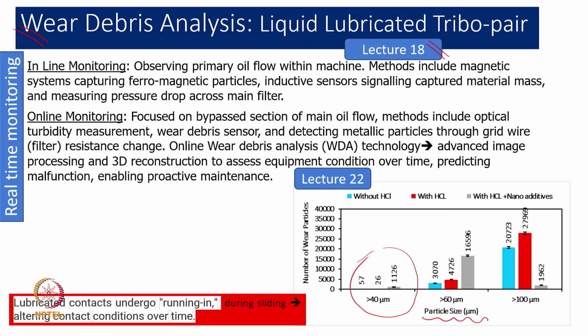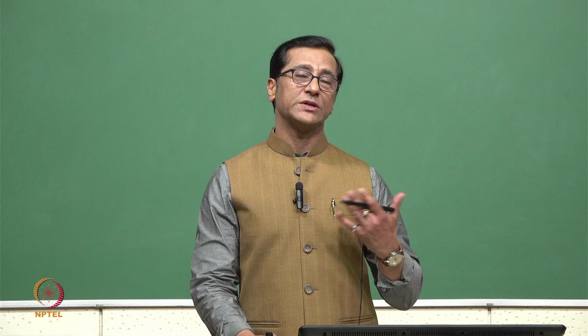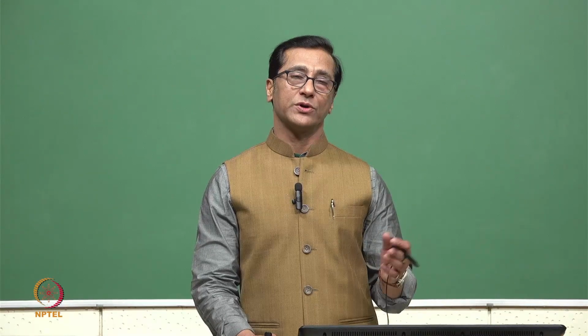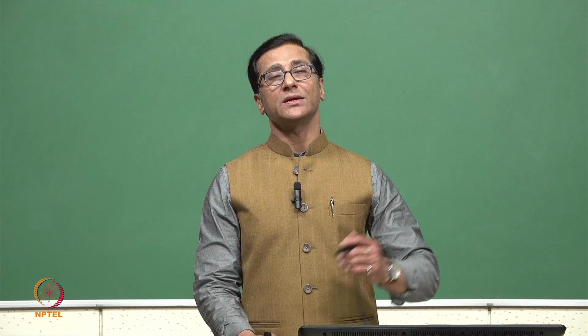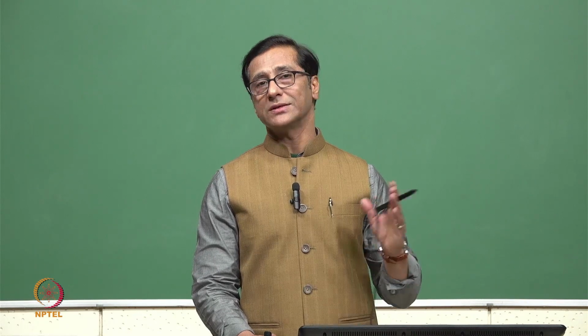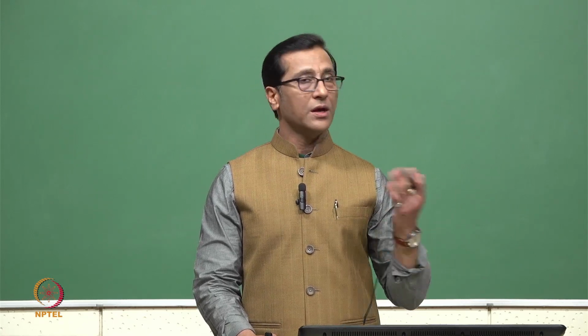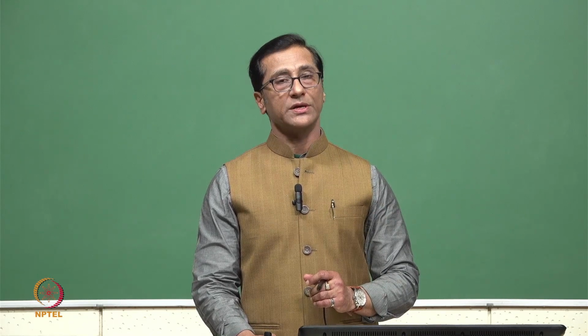If wear debris is increasing in size, and when it comes to the medium range, we can say it is mixed lubrication. If it goes to a much higher size, then we can say it is boundary lubrication. So this is a way we try to quantify what is really happening. If there is no wear particle, or once in a while it happens because of start and stop, we can say that the lubrication mechanism is hydrodynamic, aerodynamic, aerostatic, hydrostatic or elasto-hydrodynamic.